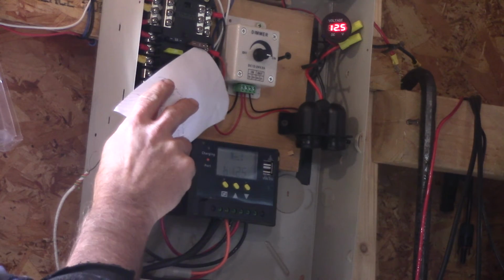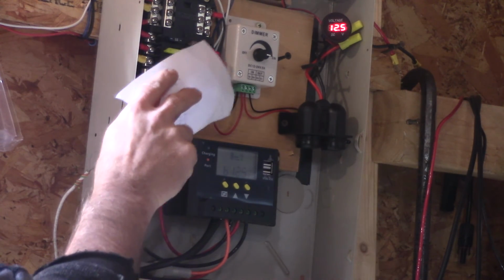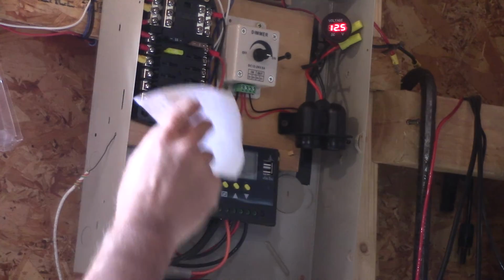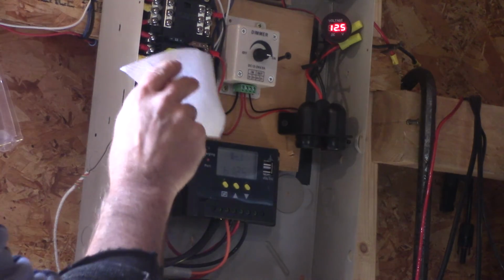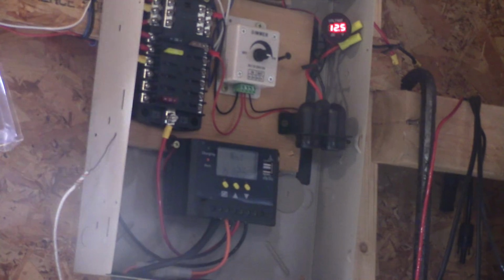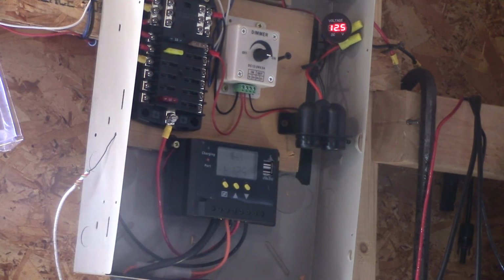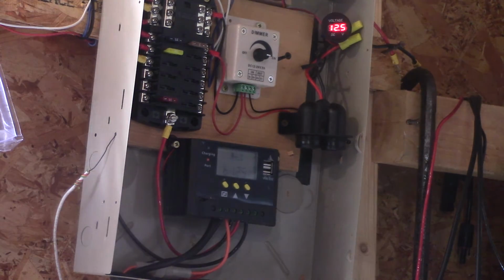That protects my lighting circuit and my fan circuit if I wanted to run them both together. You may want to run a 2 amp fuse or a 4 amp fuse, but 5 amps, since I'm running 60 watts here, I only need the 5 amp fuse because that covers me. 5 times 12 equals 60, right? So those are the things you want to know.